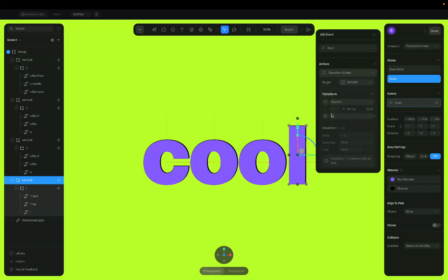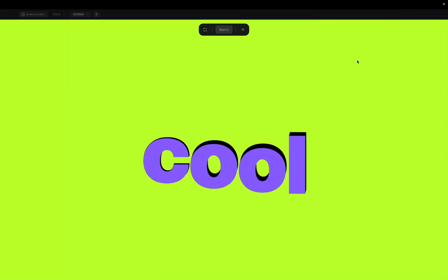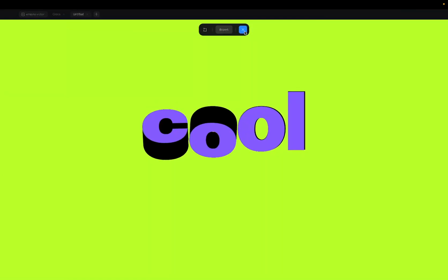So the first thing I want to change is the 2. There's nothing selected, so I'm going to select the new state, which is supposed to be called down, but that's fine. So click on the spring, and then go to the delay section and add 0.1 to the delay. So this is delayed 0.30, this is delayed 0.20, 0.10, and then this is not delayed at all. So that's how the thing goes. Then you can press play, and you can see that it has this bobbing motion.